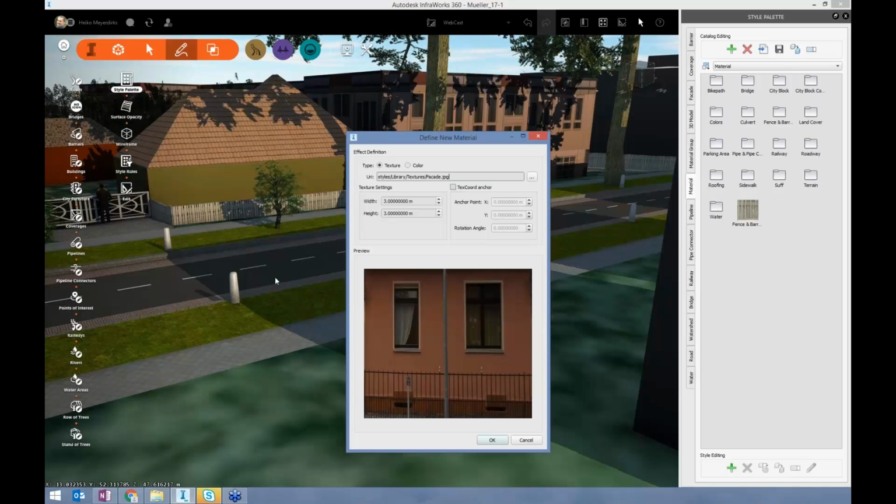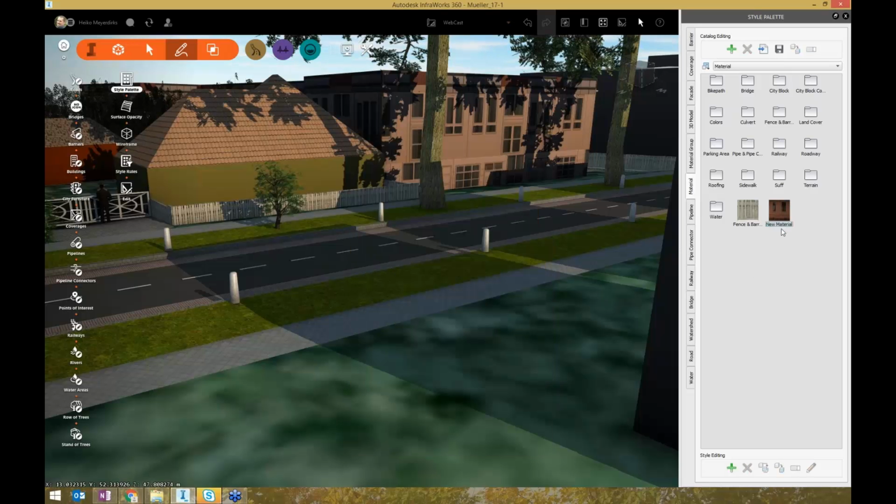So here's the width and the height. This is something you'll have to do, even if it might not feel reasonable, because if you have a picture, the system doesn't know the scale, so you have to scale it actually. Let me think of the width. Maybe the width is 5 meters something. The height is 2.5. What you see on this picture. Okay, and that's it. New material. I give it a name. My house.